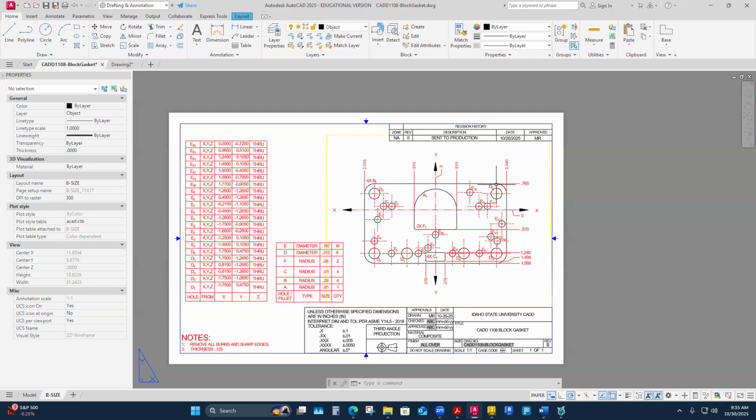Maybe I'm not pulling the overall size of these; I'm just pulling from the datums to their extents. I'm also doing that with these features of size that aren't captured in the table. That's why I've strategically chosen these as the dimensions that need ordinate arrowless style dimensioning, to capture the rectangular features of size and some of the overall part size.